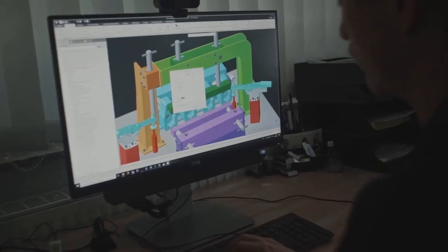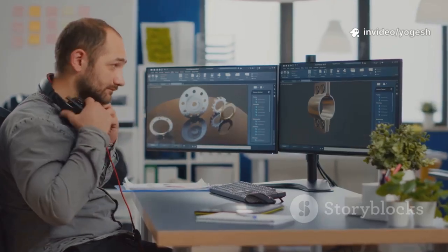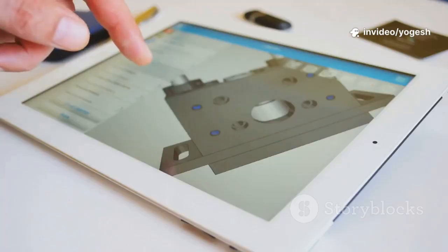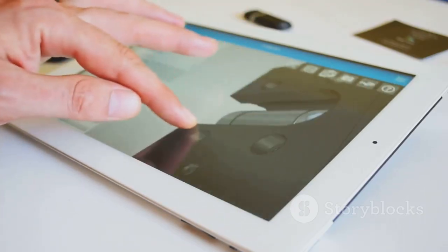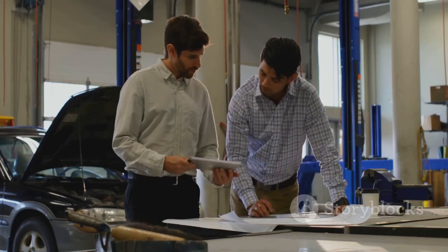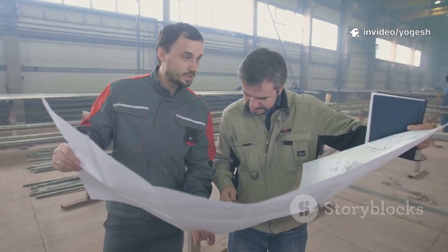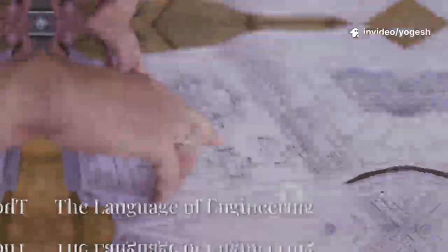Always update the 3D model first, then the drawing, never the other way around. This keeps everything in sync and prevents discrepancies. Embrace the single source of truth, the 3D model. Discipline and collaboration are the keys to reliable drawings. These best practices ensure quality from design to production.